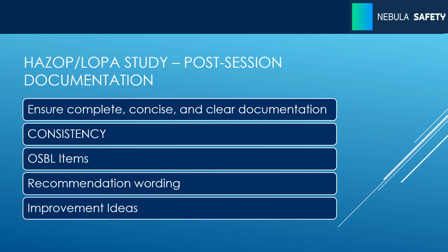We also don't recommend adding the word "consider" at the beginning of the recommendation because too often it is closed by considering the options and then determining that the current configuration is adequate. That's kind of a running joke. You say consider adding a safety rated valve for this particular scenario. And of course, someone comes along and says, I considered it, I'm not interested. Obviously, there is a risk there. The team identified the risk, and both legally and if there was an actual incident and that recommendation closure was read, it would not work out well for the person who made that determination.